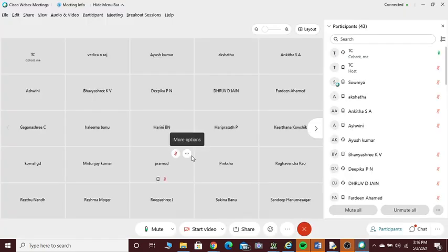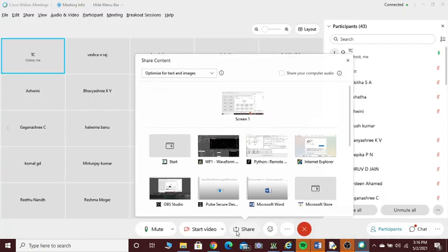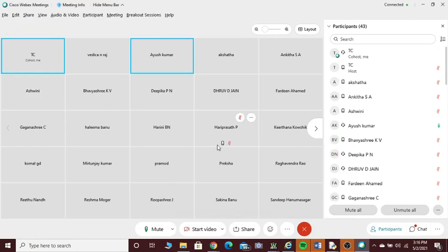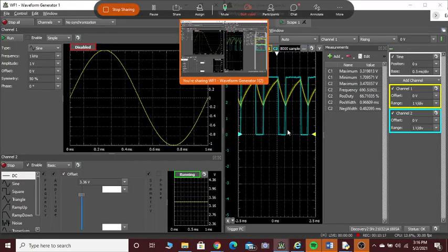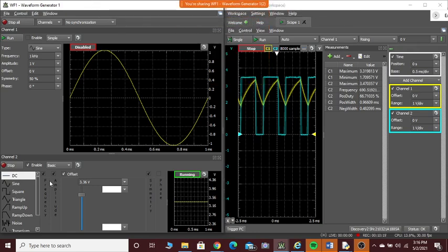That is, okay, it's disconnected. I'll just connect it. Can you see now? So we are not applying anything here. We apply the DC voltage. We will measure the maximum and minimum of channel 1. What does channel 1 indicate? Channel 1 indicates not the trigger, but the capacitor charging and discharging. It is the timing capacitor charging and discharging that it is indicating.